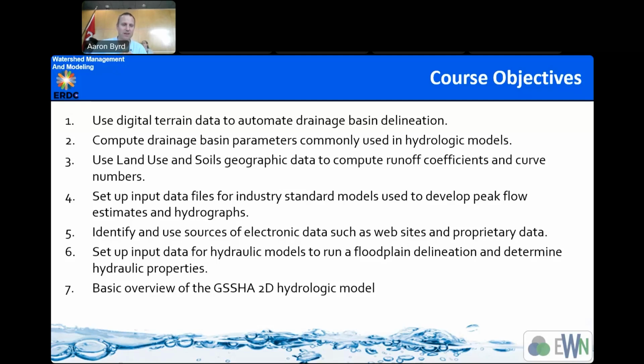Then you can create your grid, which you've seen GSSHA grids in previous slides. And then you can build your stream network, your stream model that's part of GSSHA, and then just run GSSHA. You can run GSSHA from WMS. You can also run it from just outside of WMS. Either way, if you run it from WMS, it's a little bit easier because it brings up a window.